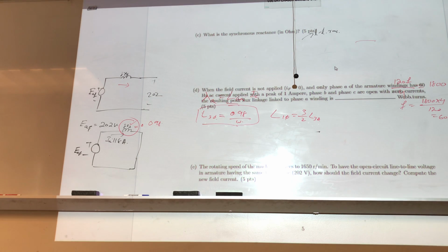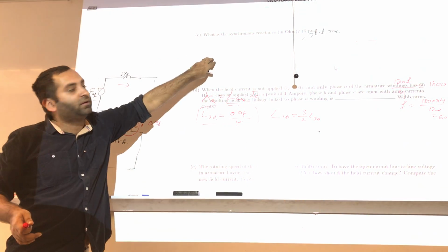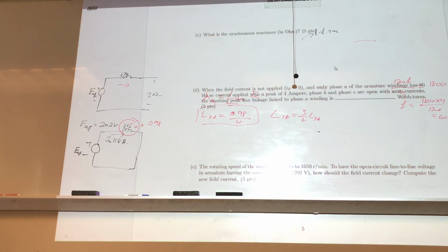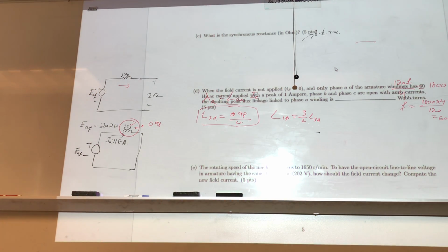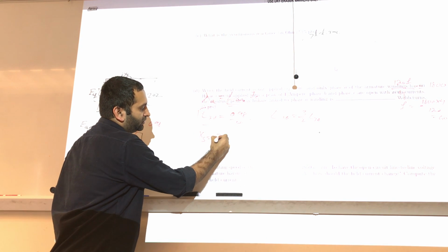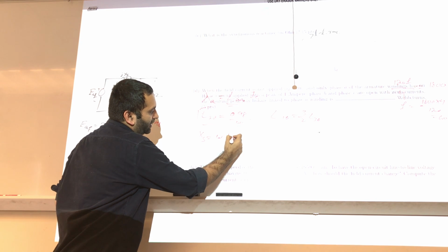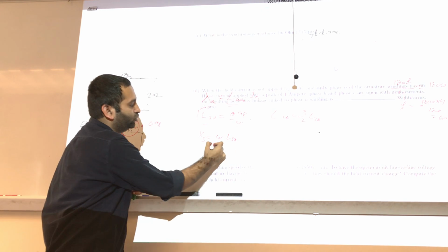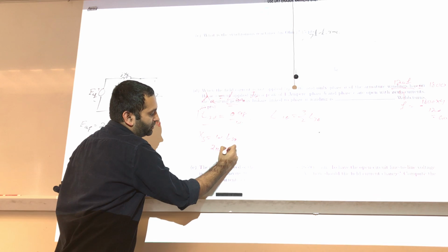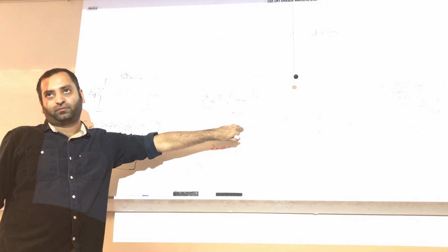So it was 0.98? Like what value was that? This value of the X_s that we found. Okay. So the general formula should be X_s over omega. Yeah, because what is X_s? X_s is nothing but omega times L3 phase, right? Because 2 pi f times L3 phase, right? So from there we found this.